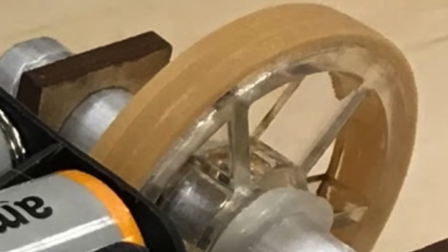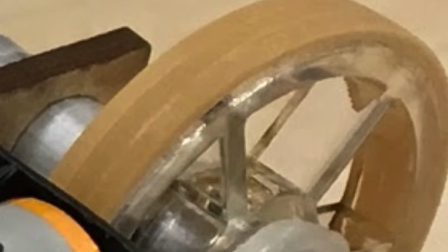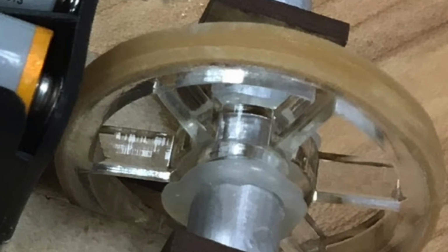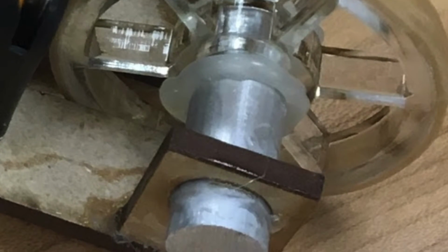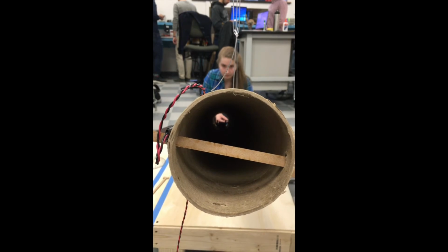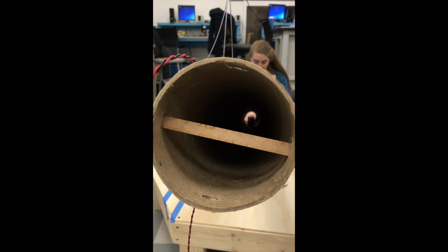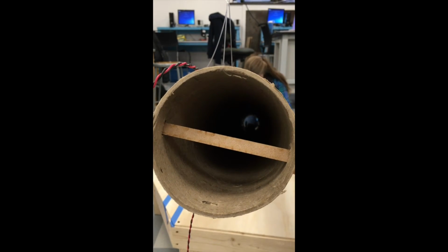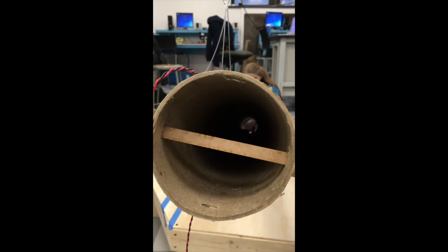However, since no thick rubber bands were available, multiple thin ones were cut, lined up side by side, and glued to the front wheel. There were concerns that this was not precise and would decrease the roundness of the front wheel, impeding motion. For the back wheels, originally rubber bands were placed around the wheels but were not secure when testing and slid off. During our initial test, the car failed to travel up the 15-degree incline. We speculated that this was because the rubber bands were not in contact with the tube on the back wheels and did not have enough friction. After the rubber bands were glued, the car was able to travel successfully up the incline of the tube as predicted.